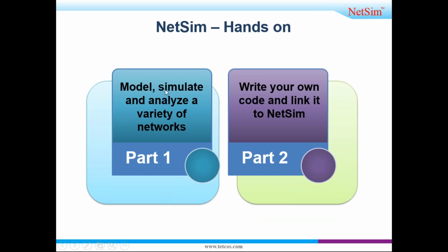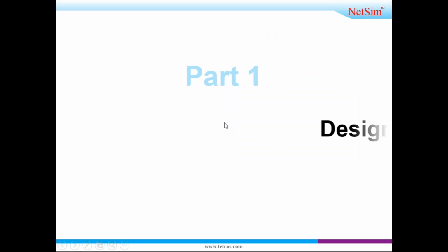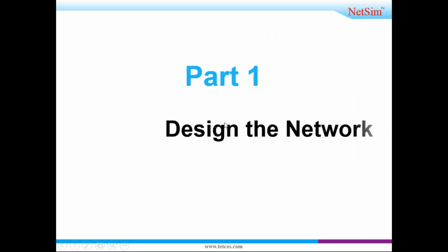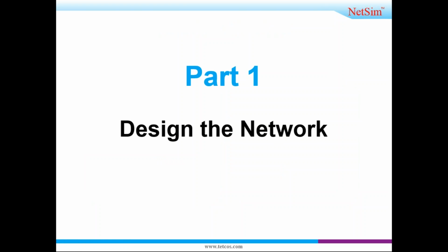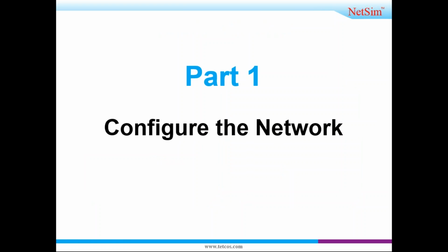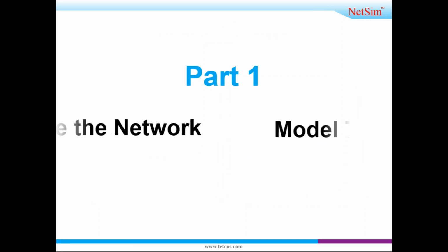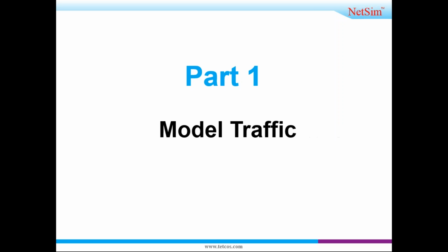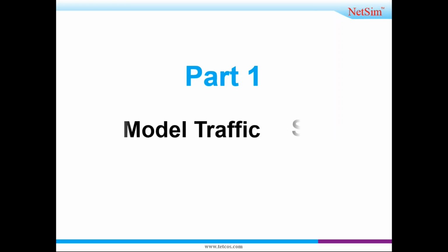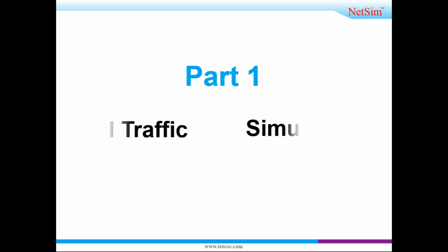Now the hands-on is divided into two parts. One is model, simulate and analyze, and then write your own code and link it with Netsim. So we just go to part 1, where we can design the network, configure the network by setting the parameters, and model traffic, where we can generate various traffic on any node and simulate the network.